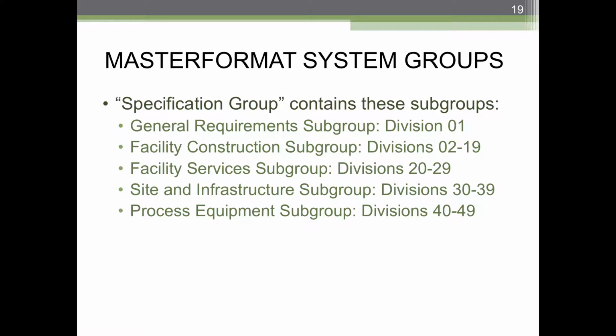When we get to spec writing, we will cover this more. The only thing that actually is critical at the early stages of design is that you should be aware, as you create your elements in your Revit projects, that the family types within Revit can be used to generate these MasterFormat specifications, but you have to use the product information that you know is in there. So often, in an early stage in the design, you might be just using kind of proxy objects that are masses or other things. But as soon as you can, put in objects that follow that, or at least have this CSI information in them. And you may not even have ever noticed it, but in the properties of your typical door, it may have the CSI section in there.